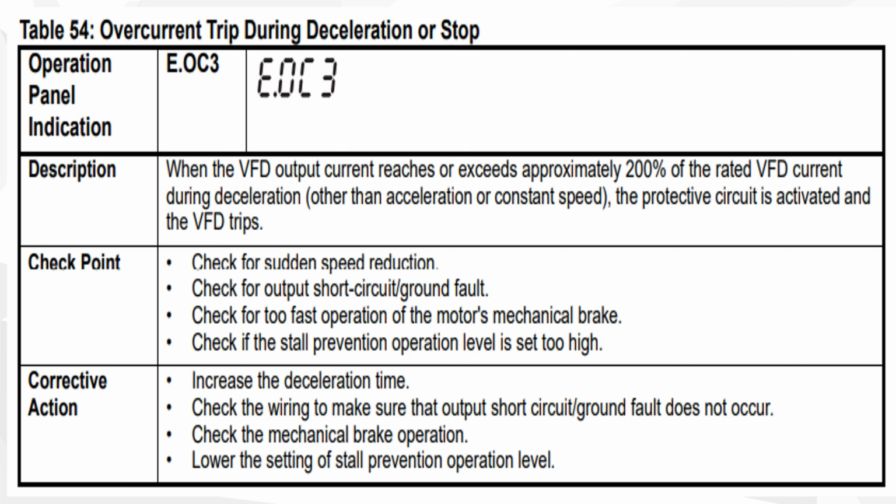And another thing we have to check is that there could be a brake on the motor output, a mechanical brake. It might be that the motor is stopping early because of the motor mechanical brake. So we have to check that also, like when the VFD frequency is 0, then the motor mechanical brake should be activated. And we have to check the mechanical environment, like the belt or conveyor, that it is not too tight.